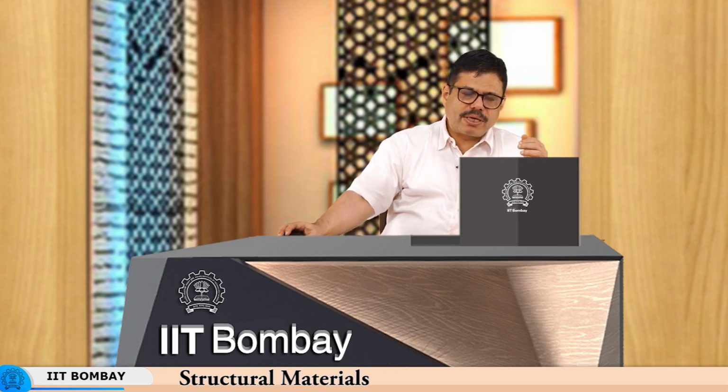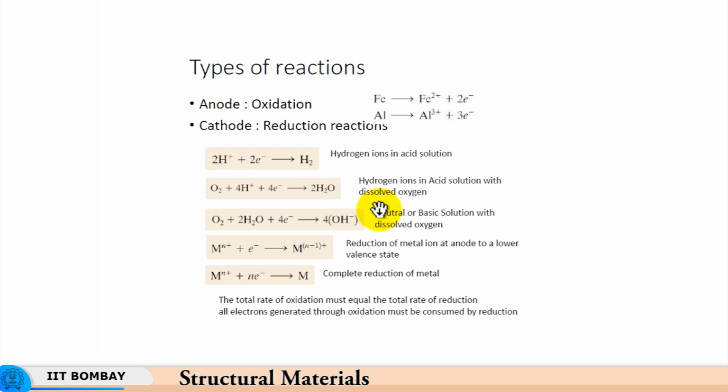So, if the electronegativity of that particular element or phase is towards the anodic side, then that will go into solution first, whereas the other alloying elements which might have been added would remain in the metal in an alloyed condition. So, whether a particular alloying element A will go into solution or not will be determined by whether B, C or D is present.